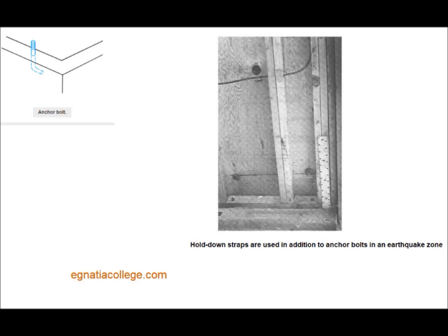In concrete foundations, anchor bolts are placed in the top of the foundation. These bolts are left protruding out of the top of the foundation so that the wood superstructure can be fastened in place later. Anchor bolts are not normally shown on the foundation plan, but a note on the wall section indicates their spacing. On masonry walls, anchor bolts can be placed in the hollow cores of the concrete blocks.